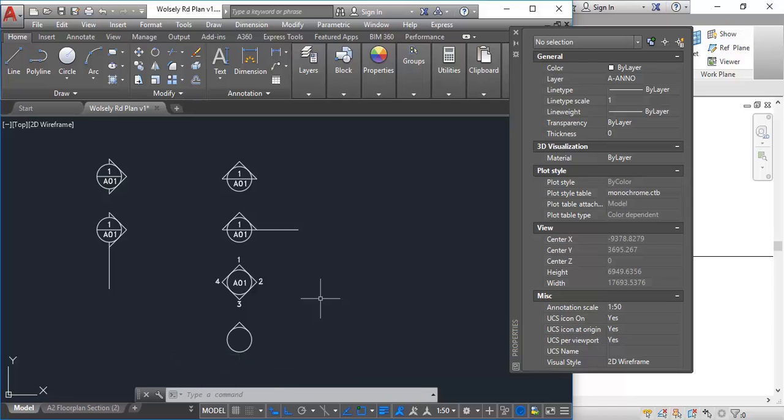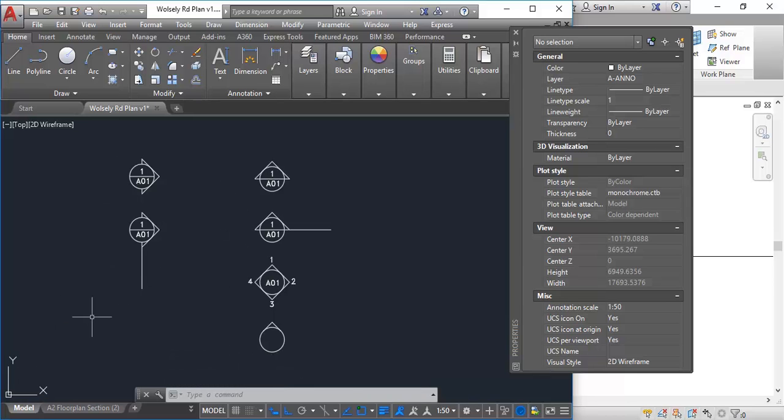And that's the last major thing. So again, I'll just say it one last time, the annotation is the key. It's something that a lot of people, until you have done a few of these drawings, think is just something you do at the end and maybe focus on all the line drawing. But then when you've done a project like this and when you get hired to do construction drawings for a living, you'll realise that the notes are as important, and probably in many cases more important, than the lines and the other things you draw for your buildings and your building elements.